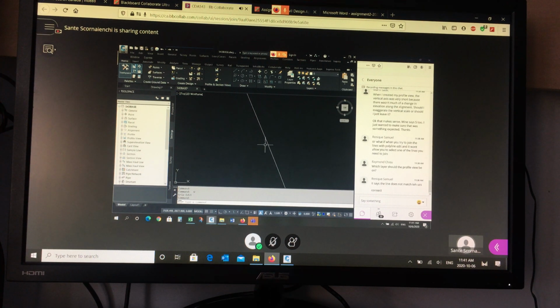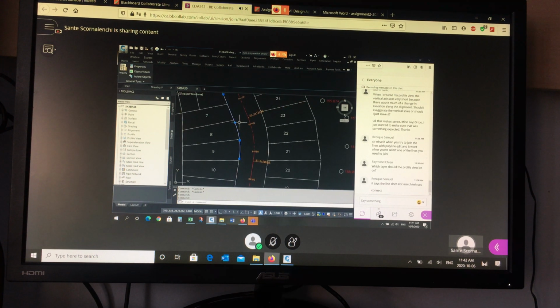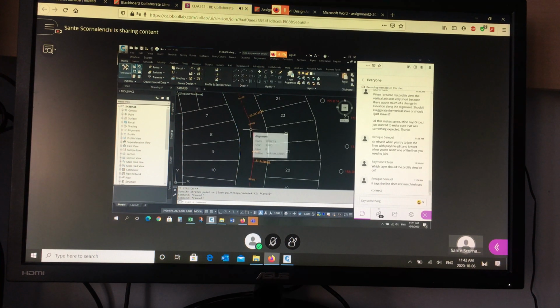And like I said, as long as they're different, even in the 10th decimal place in terms of distance, it won't connect. So you have to be careful. But that's a test before you start. Click on both. If that's supposed to be the same, when you click and drag the grip, the end of both entities should go together. If only one goes, then there's a problem. So then you have to look at redrawing.